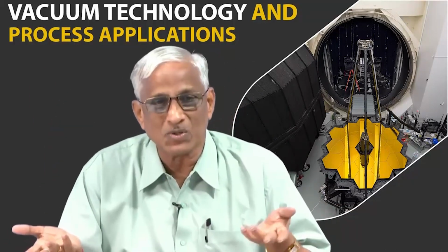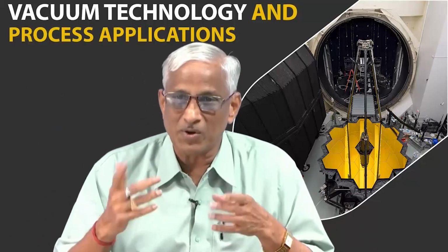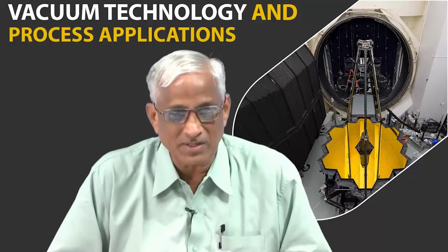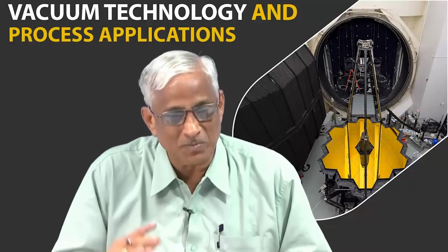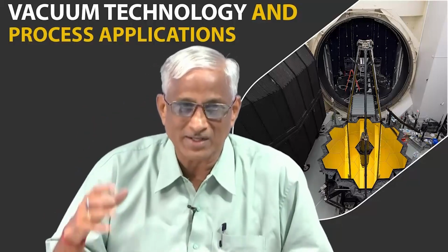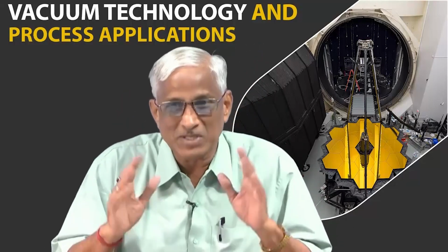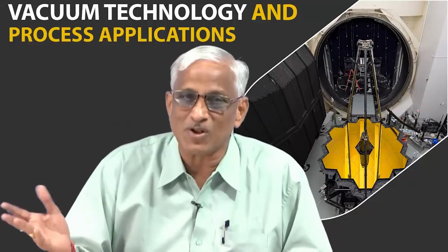Again with that load you can test the chamber. When you are loading, the total load, that is called total throughput, should match the effective pumping speed available at the chamber, and the working vacuum, the equilibrium vacuum, should be satisfied. Then only the customer will also be happy.